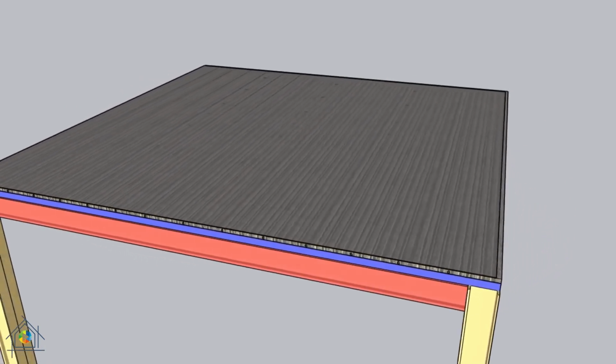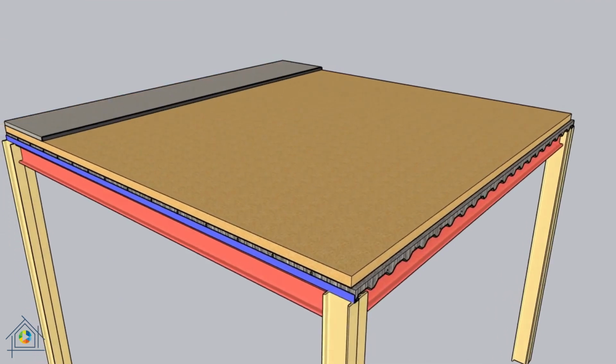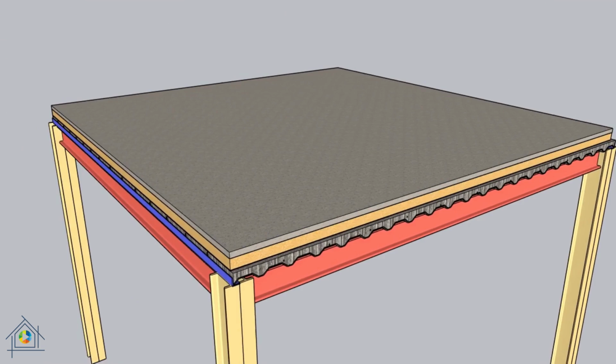A layer of thermal insulation, for example rock wool, is applied with a minimum thickness of 5 cm. On the surface of the thermal insulation, for leveling and sloping, lightweight concrete with a cement content of 150 kg per cubic meter or mineral pumice is used. The thickness of the leveling section is at least 5 cm.